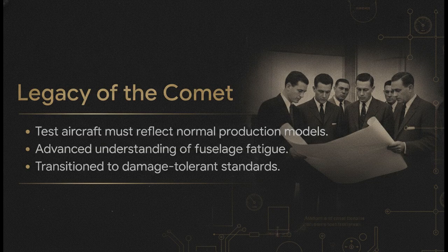Now, we shouldn't exaggerate and say the Comet changed absolutely every single aviation standard in existence, but its legacy is undeniably profound. This grueling forensic investigation served as an enduring lesson. It proved definitively that a test aircraft must accurately reflect the normal production models operating in real service. It vastly advanced the world's understanding of fuselage fatigue, and it paved the way for the transition of early safe life and fail-safe designs into the incredibly rigorous modern damage-tolerant standards that keep us all safe today.